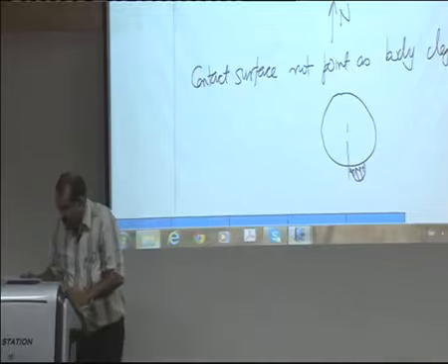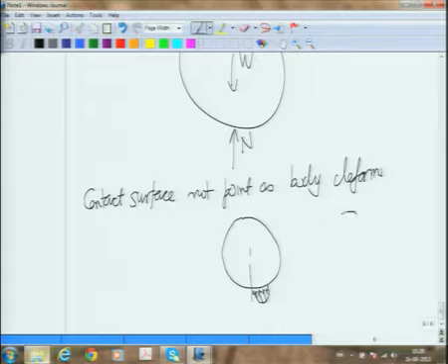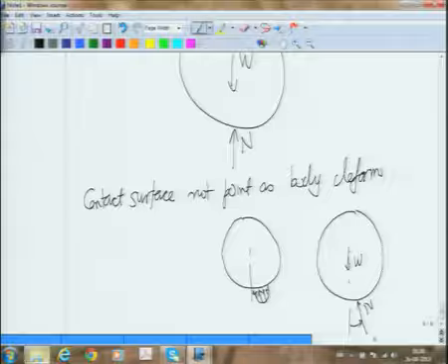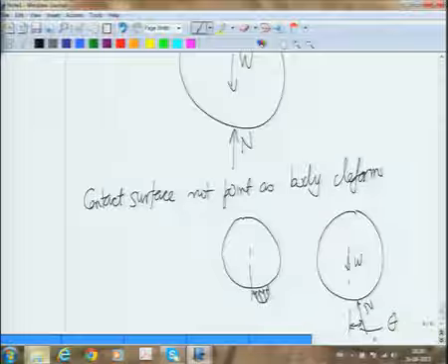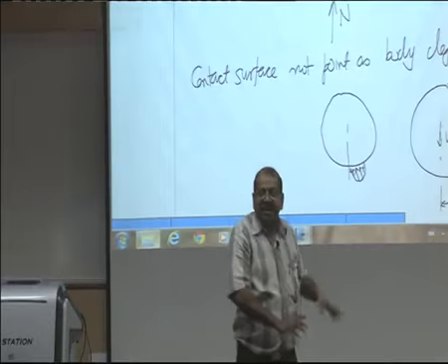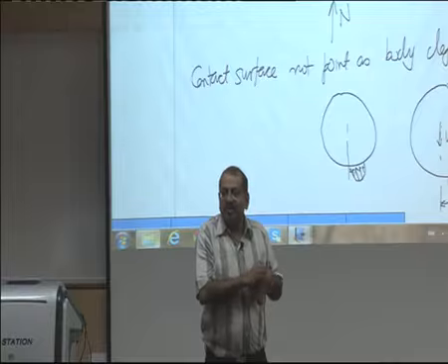When we draw the free body diagram, we have the weight acting here, and the normal force acts at a small angle theta. This N represents the integral of all these forces, and because each of them passes through the center, this integrated N will also pass through the center.